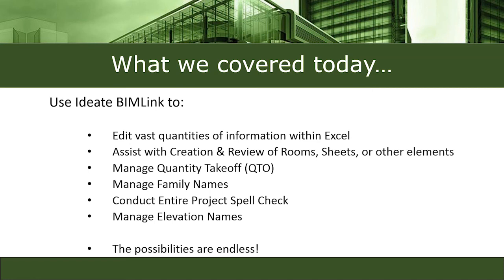I have some other examples that I sometimes show with MEP, where we've got device elevations, like the sockets, which are at a particular elevation and maybe they're wrong. So you can send it out to Excel, update the device elevations to the correct information, maybe 100 or 500 of them, very easily, import that, and now they're changed within the project.